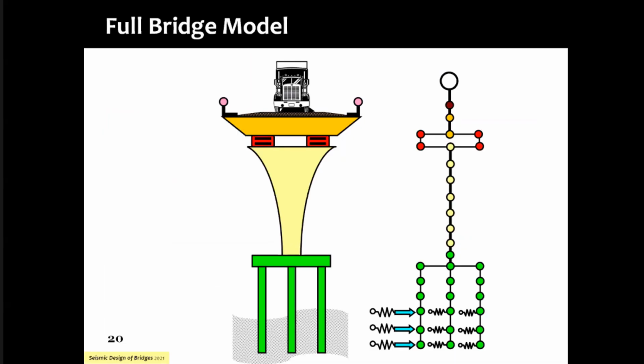So there is a need to understand how many nodes you will model, and especially when you have geometries that are exotic, you will get into great headaches of trying to idealize each of the slices, and you cannot make too small a slice and you can't make too big a slice either, and that is why you have to be very careful.